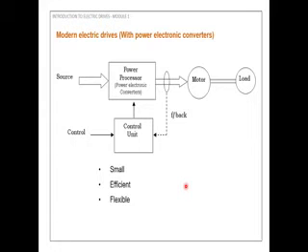So for controlling purpose, we have a sensing unit and a control unit. The sensing unit is nothing but a speed and current sensor, so the speed of the motor can be easily sensed and given as the input to the control unit. The control unit has two inputs. One is a standard input, that is, the rated speed of the motor, and another one is the actual speed sensed from the motor. The control unit compares these two inputs and finds the difference or lag between the speeds.